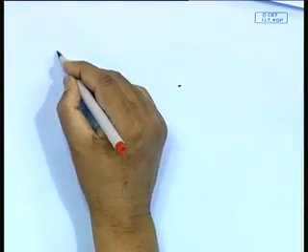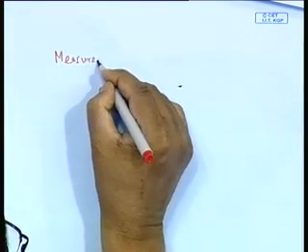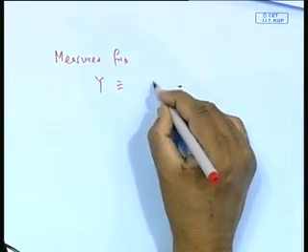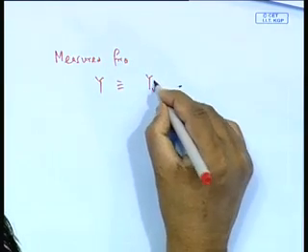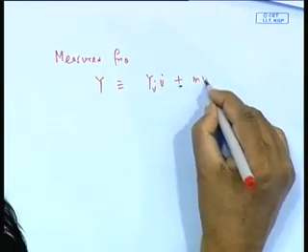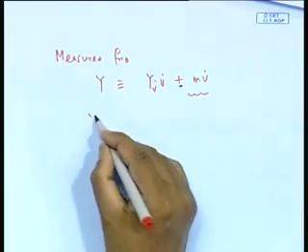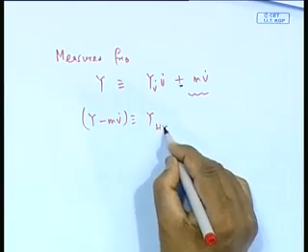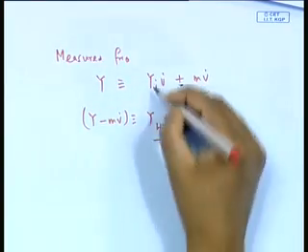In other words, what I am saying is that just think of this, the measured force, say Y, will always include, just to give an example, Y_v dot v dot plus m v dot. This part also is included. So, if you want only this much, what you could do is subtract m v dot and define this to be Y hydrodynamics, and then take Y hydro divided by v dot to get Y_v dot.